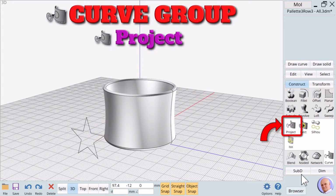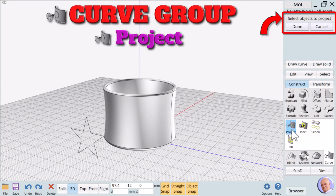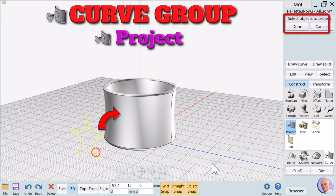We click on the project button. The prompt reads, select objects to project. We select the star and click on Done.